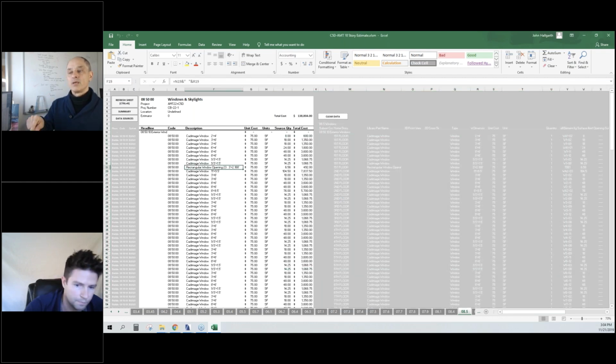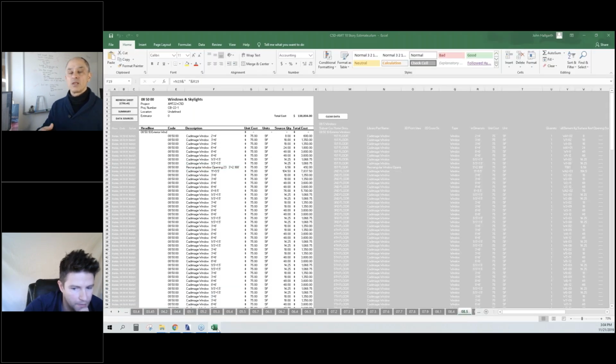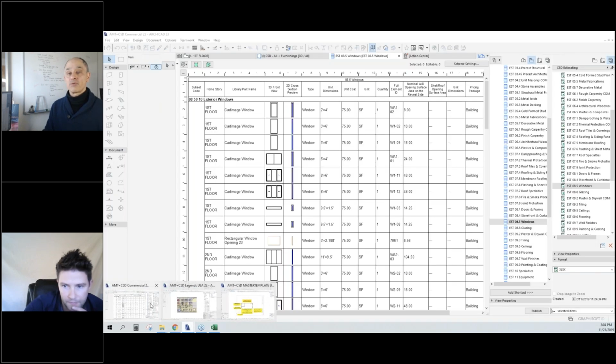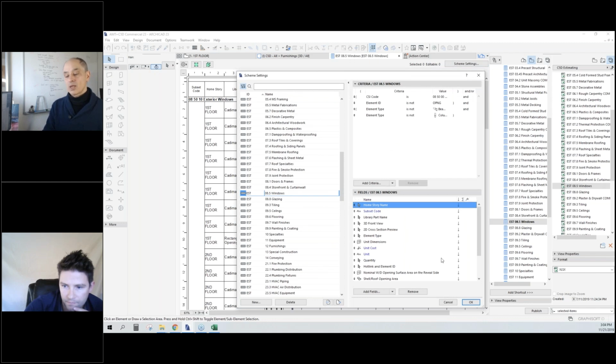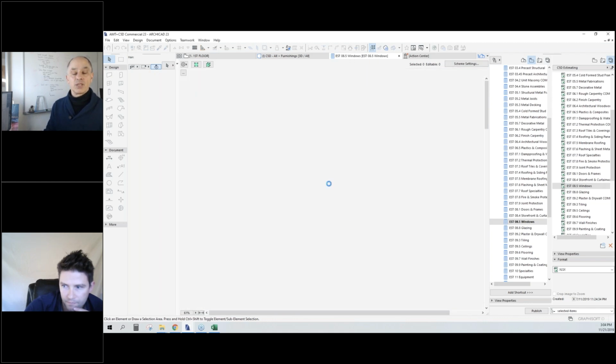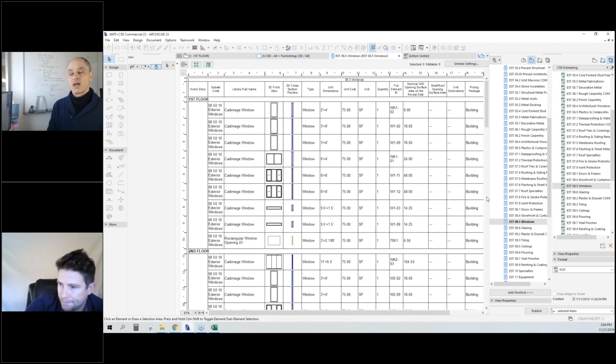You can eyedrop wall types, windows, objects, and have them already set up as you drop them into a project in the right schedules with at least some initial costing set up. And then you can actually refine the legends so you have your costing in your local area and keep that up to date. It's going to allow you to very quickly manage and update your quantity costing.